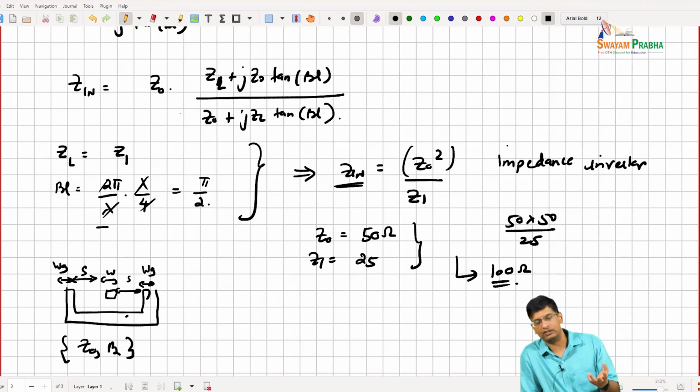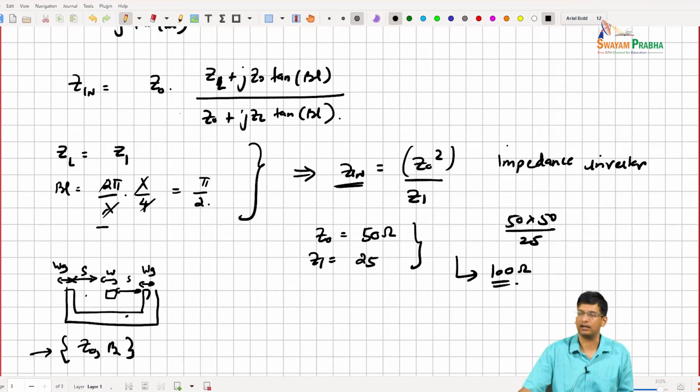And all simulation tools give you an opportunity to model or use ideal transmission lines if you can provide these coefficients into them. So you can design your circuit, and then when it comes to layout, you just use the model that you've developed, that transmission line of appropriate length, right? So it's a very convenient way of designing at millimeter wave.